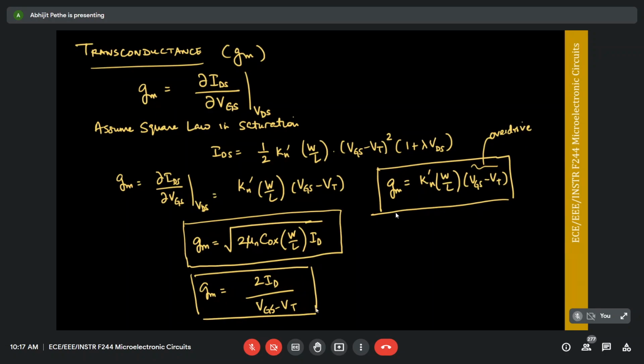is simply because many times you have flexibility in choosing only one or the other. So depending on what circuit parameters you can change, based on that you can design the circuit using either of these formulae, right? So again, they're all based on the same, but what you see is essentially GM, and this is again an important relationship. GM is completely controlled by the drive current and the overdrive, right? So the higher the drive current, you get a higher GM, right?